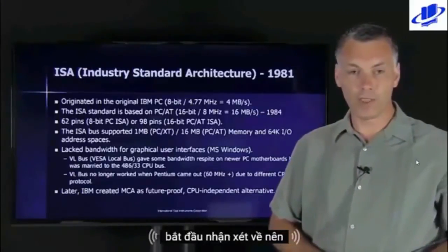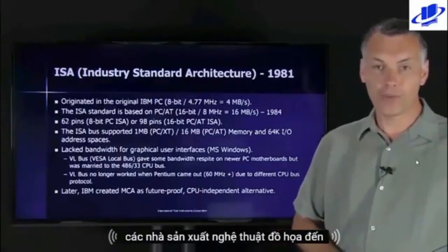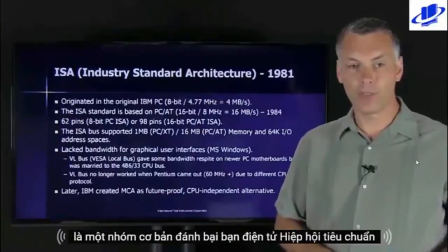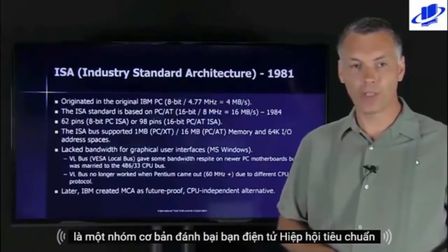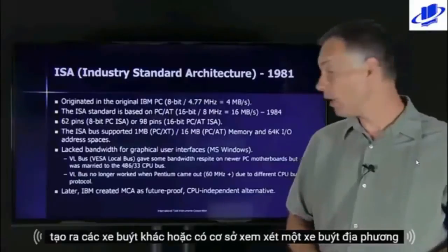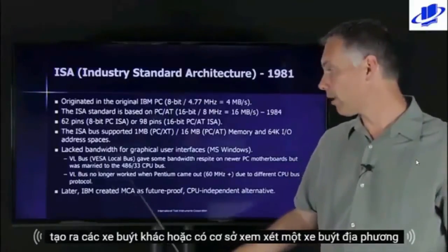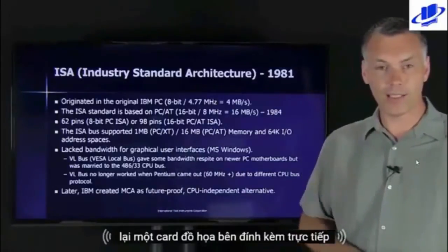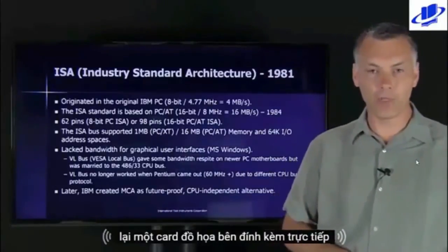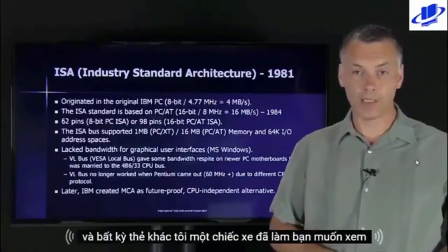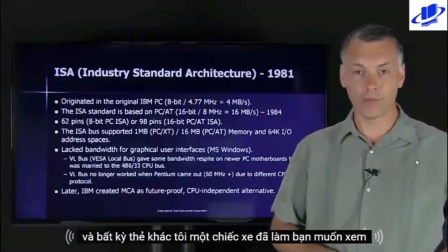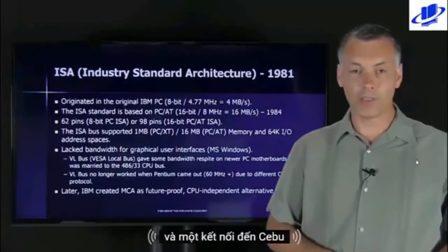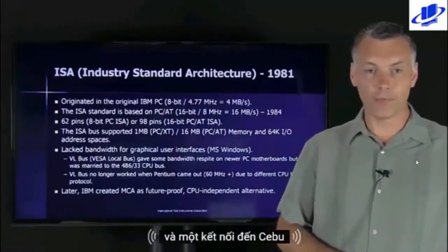So the graphics card manufacturers came together and through their group, the VESA group, Video Electronics Standards Association, created the VL bus or VESA local bus, which essentially was again a direct attachment of the graphics card and any other I/O card that you wanted to directly connect with high performance, and they connected it to the CPU memory bus.